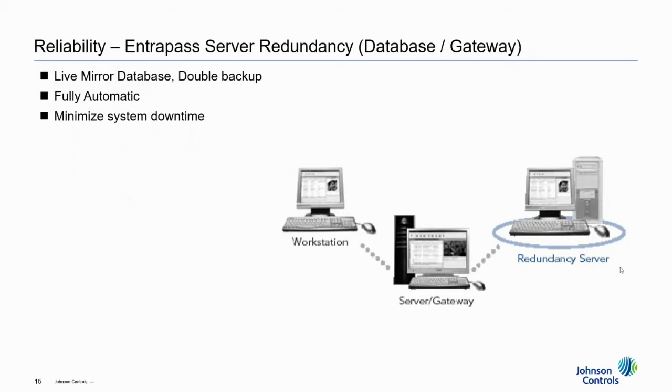How KANTECH works is that all your controllers must be connected to a gateway. The gateway is like a cache, whereby it caches all the information and allows all the controllers to intercommunicate with each other. The gateway communicates with the server's database. If the site is small, effectively both the server and the gateway reside in the same machine.